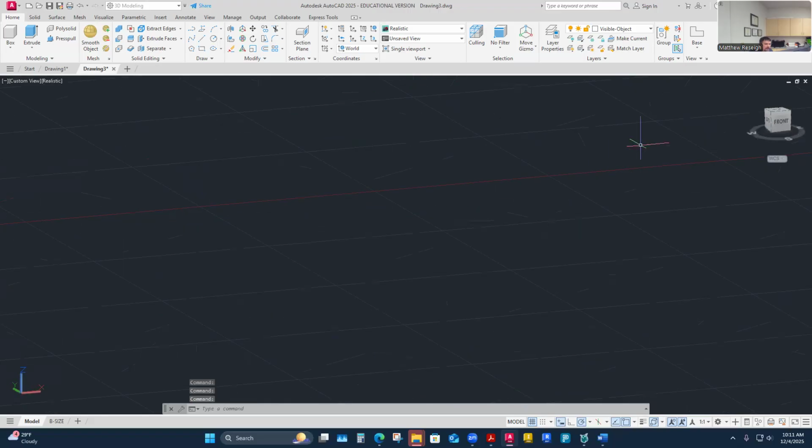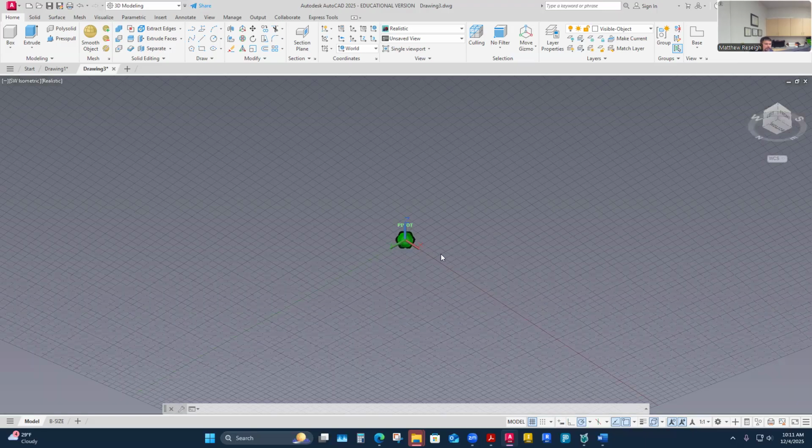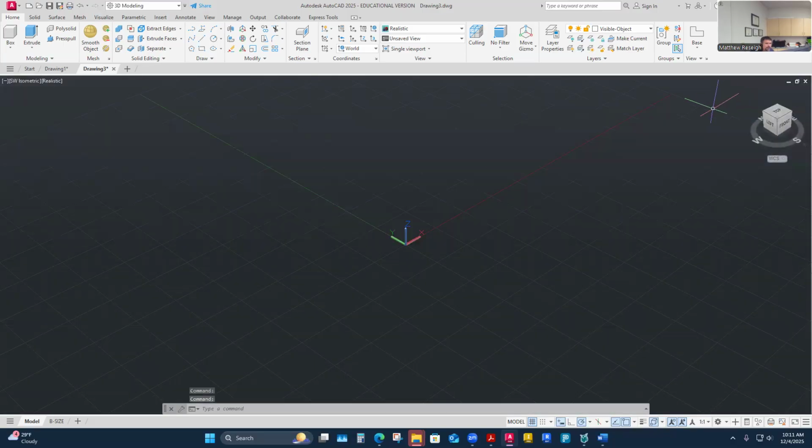And when you get totally lost, there's this little home button here. Usually this will zap you to what you've drawn, the home view of it. So I use the home view if I've rotated around and I'm totally upside down and I don't know how to get back. If you click the home button up here, it'll usually orient you like this, generally. Oh yeah, like a zoom extents, that works as well.